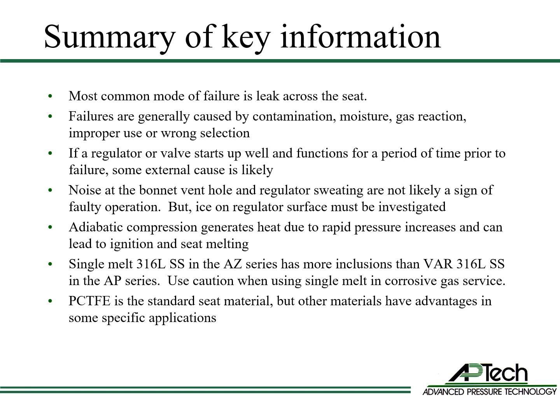Now let's review the key information regarding failure modes. The most common mode of failure is leak across the seat. Failures are generally caused by contamination, moisture, gas reaction, improper use, or wrong selection. If a regulator or valve starts up well and functions for a period of time prior to failure, some external cause is likely. Noise at the bonnet vent hole and regulator sweating are not likely a sign of faulty operation, but ice on a regulator surface must be investigated.